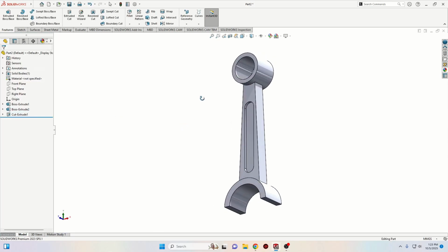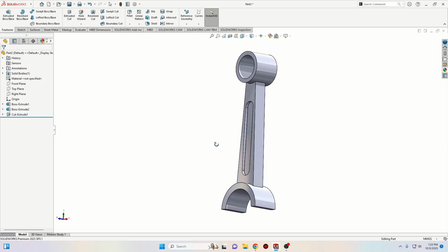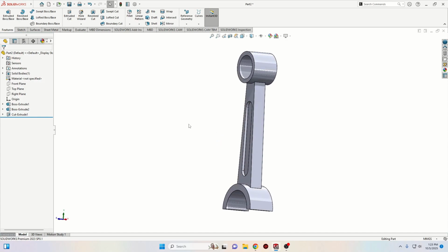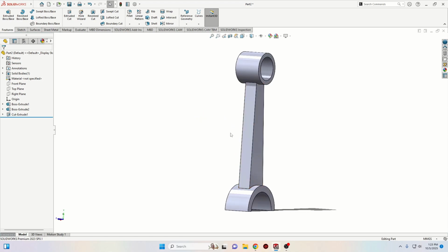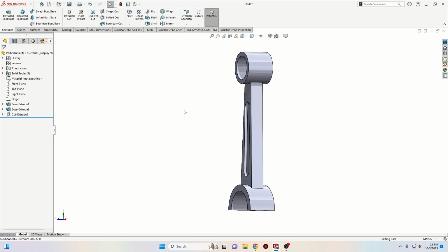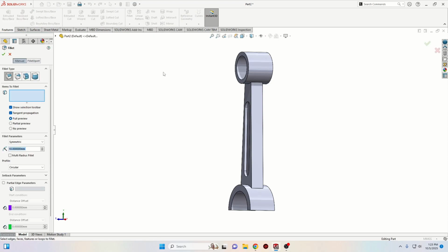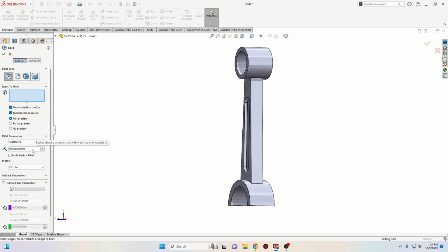Is it okay? And now we're gonna use mirror to mirror this on this other side. Now we also have to make a fillet for this, so you can make it now, and then you can also select it when you are going to use mirror to mirror it, or we can make it at the end after we make this other slot here and we select all of these lines. It's up to you. I'm gonna make the fillet now, and I'm gonna select it when I'm gonna mirror this. Okay. So the radius for this fillet will be 1 millimeter.